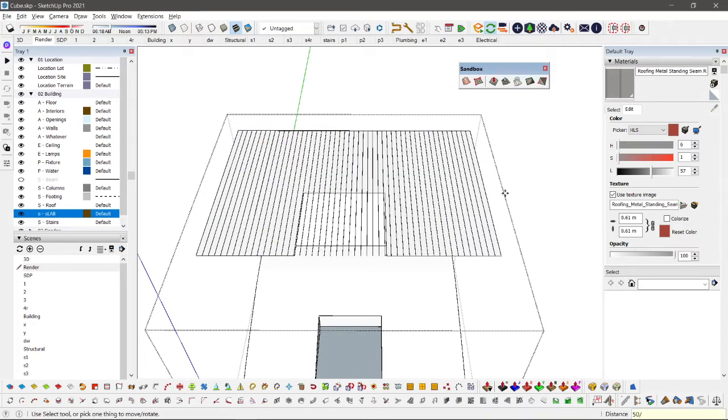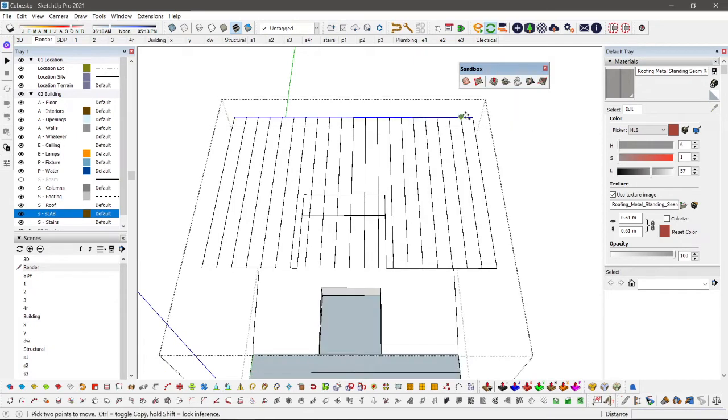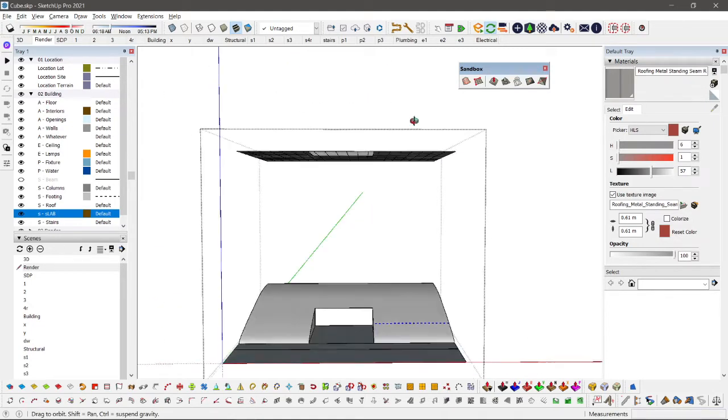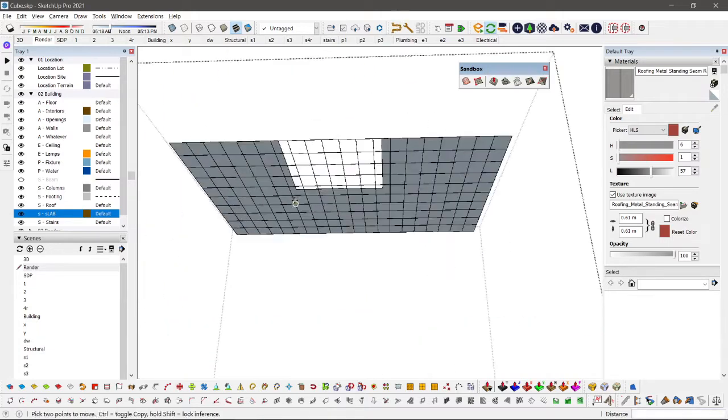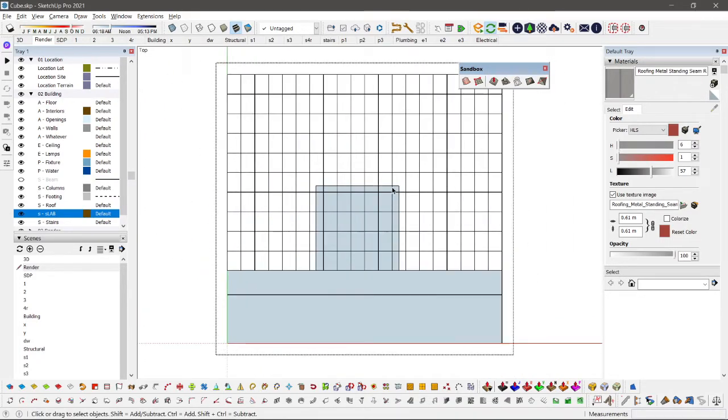That makes 50 subdivisions. It's a bit too small, it might lag, so try 20 divide. That's better. Do the same thing here, maybe 15 divide. I don't want it to lag that much, so 10 divide. Okay, and then I could delete this thing here, so I could go this way,